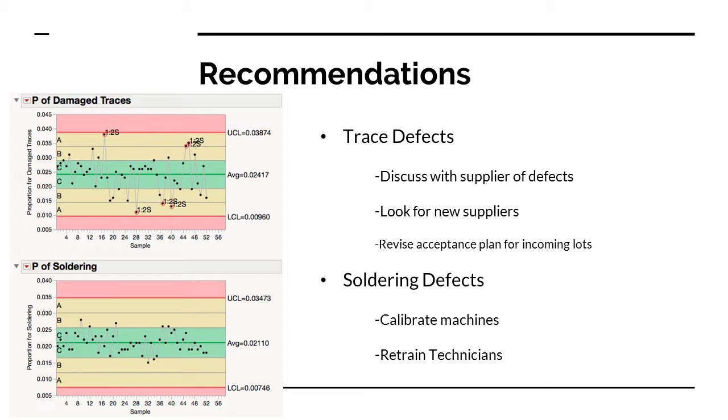After understanding that the variances were not equal, we went ahead and did further analysis with a p-chart of damaged traces and soldering. From the p-chart, we noticed that the damaged traces were much more out of spec and needed much more looking into. So our recommendation for the trace defects is to discuss with the supplier about the panels that we are getting and look at fixing these defects.